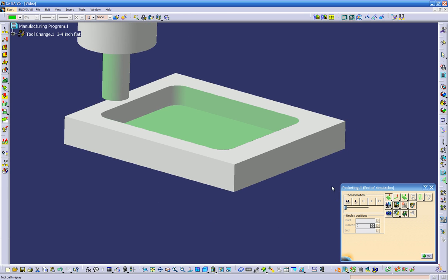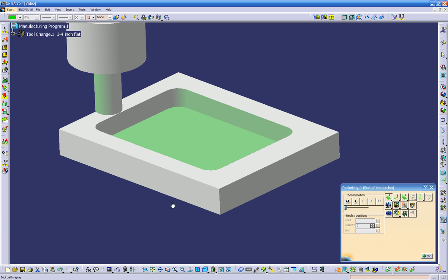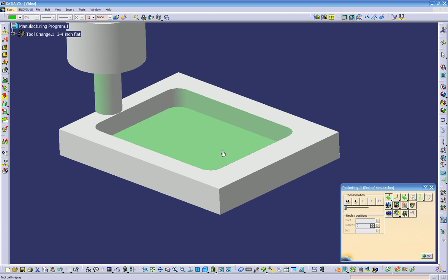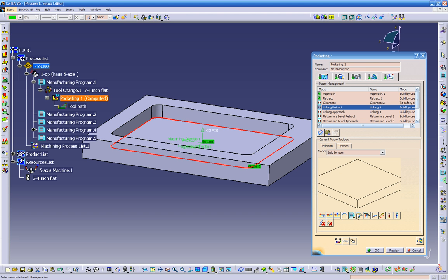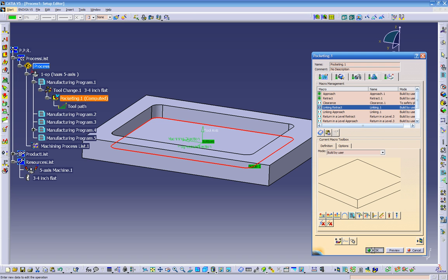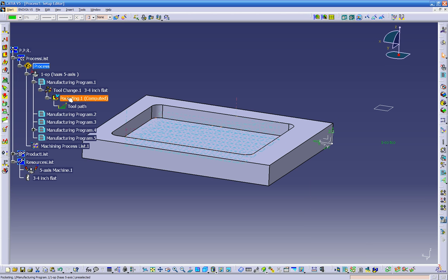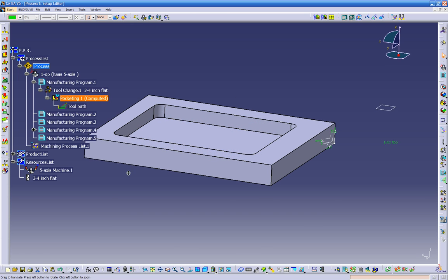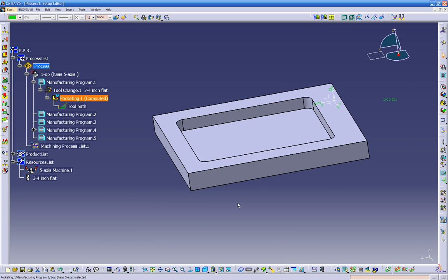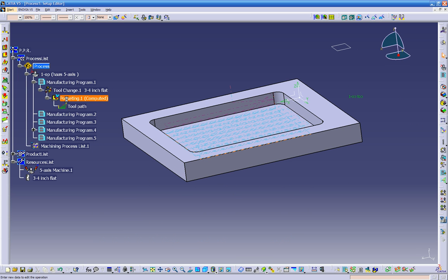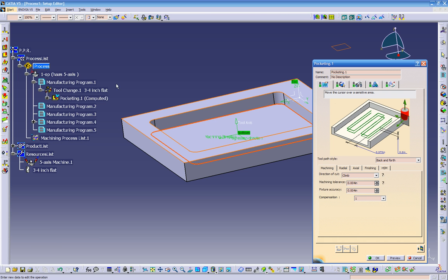And what we can do, we can save this result and pull it up later, and we can keep on going from there. So I'm going to keep this. It says it's already stored. Click OK. Over here on my pocket we get this blue mark, and it tells us that we already have a previous operation stored in there. So we can change this as much as you want. Just double click on it. We can change it to inward instead of back and forth.